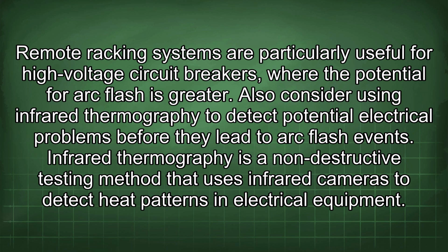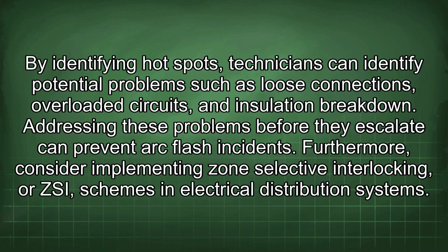Also consider using infrared thermography to detect potential electrical problems before they lead to arc flash events. Infrared thermography is a non-destructive testing method that uses infrared cameras to detect heat patterns in electrical equipment. By identifying hotspots, technicians can identify potential problems such as loose connections, overloaded circuits, and insulation breakdown. Addressing these problems before they escalate can prevent arc flash incidents.